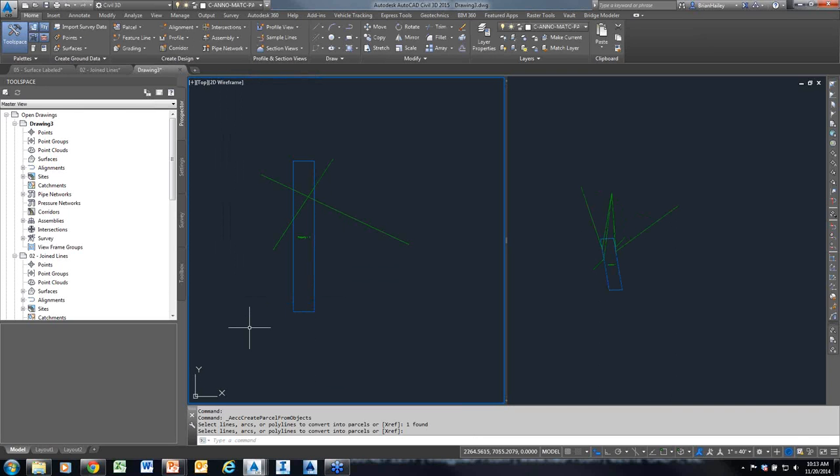And as you can see over there on the right, when the parcel segments intersect the feature lines, they always are going to have the same elevation because they're in the same site. Over here in the plan view, I don't see any of that. So the surveyor came in and froze the surface and all the feature lines because he didn't care about that sort of stuff, and it inadvertently messed up all of Sally's grading.